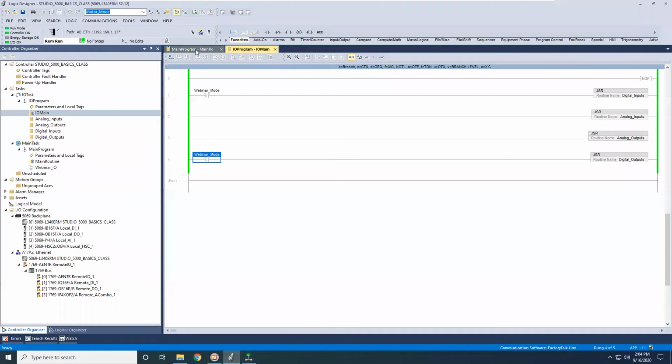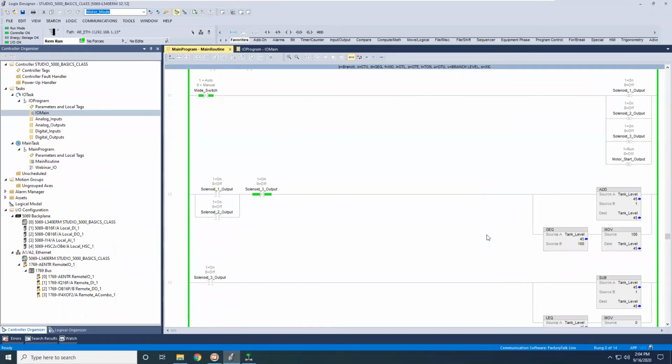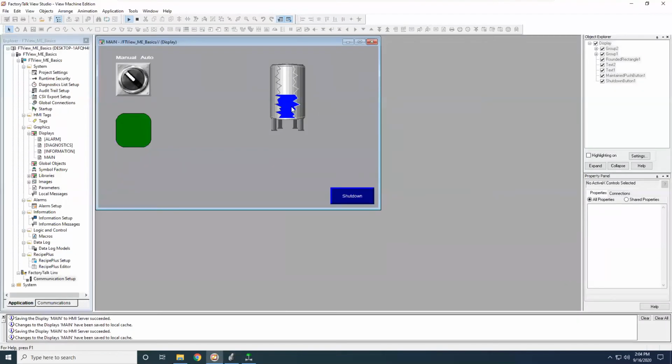And let's look at our routine again. And our tank level animation is at 45%. It looks approximately 45% of the whole object. So that's pretty good. So that's how you can add a tank level or something else like that. You would want to use a fill animation. For us, it was best to have it fill just the inside because I wanted to see the outside of the graphic. But that again would be based on preference.